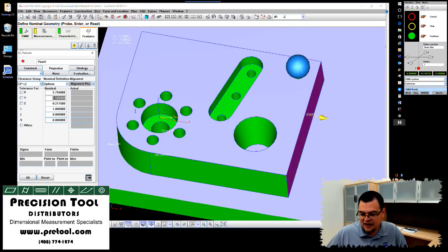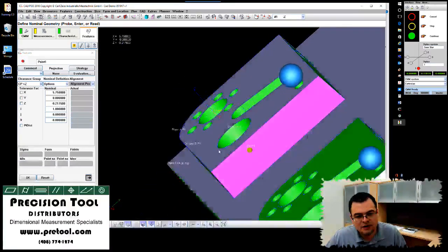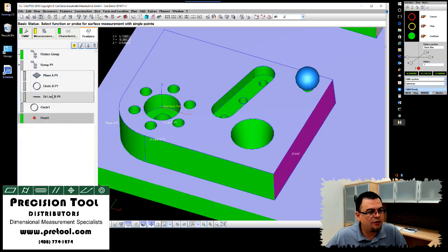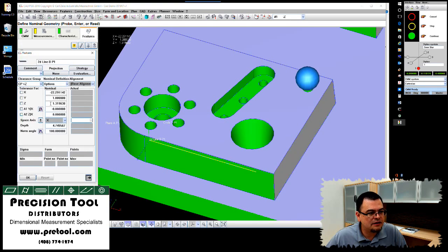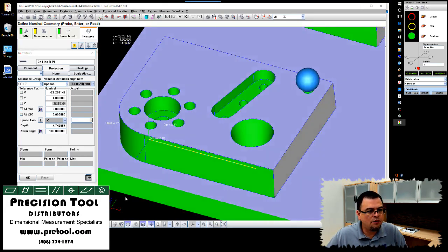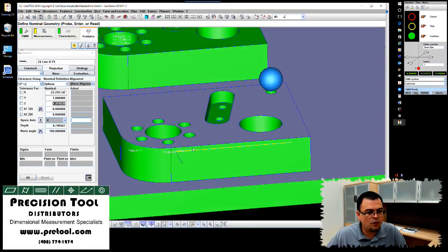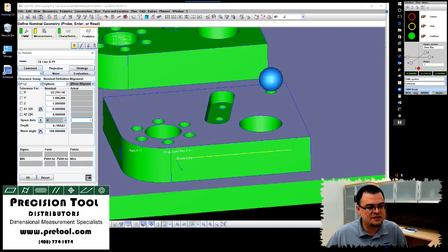Looks good. Actually, I'm just going to put that at 0, right? Why not measure the overall length right in line with the alignment, and Z minus 0.5. So that looks pretty good. Should probably put this at... interesting. So Z 1.3 is off of there. This is 1.5 thick, so Z of 1 inch is at minus 0.5 relative to the top surface.